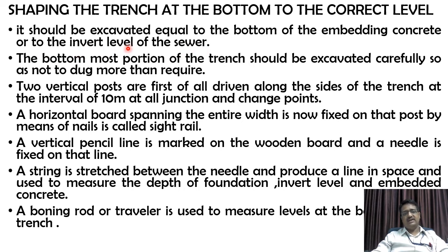Okay, so what does the invert level of the sewer indicate? The bottom level of the sewer. Invert level is nothing but the bottommost level of the sewer line. The bottommost portion of the trench should be excavated carefully so as not to dig more than required. Because if you dig more than required, then the depth of bed concrete will increase, and in turn the cost of the project is going to increase. So that's why the bottom level of this excavation needs to be maintained properly.